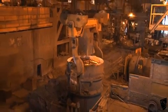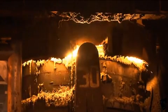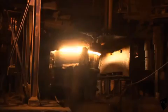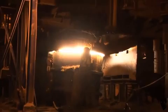In order to produce specific properties, the liquid steel from both systems goes to the secondary treatment station, secondary metallurgy, ladle metallurgy, or chemical reheating. Likewise, liquid steel can be processed in the dual degassing station to reduce the content of hydrogen and carbon for applications with higher requirements.